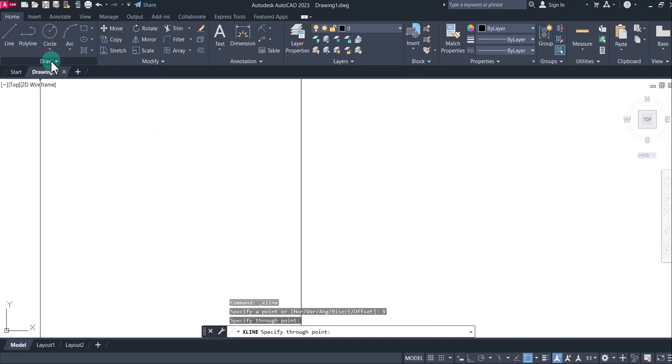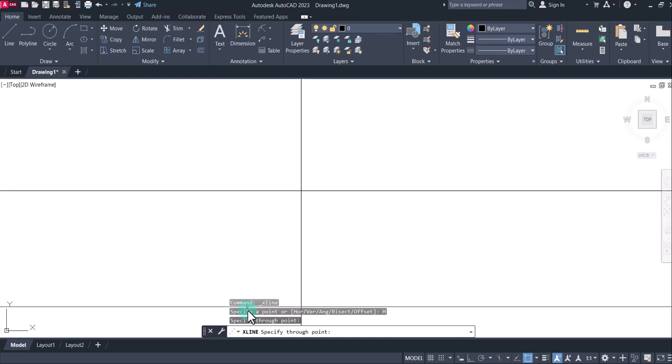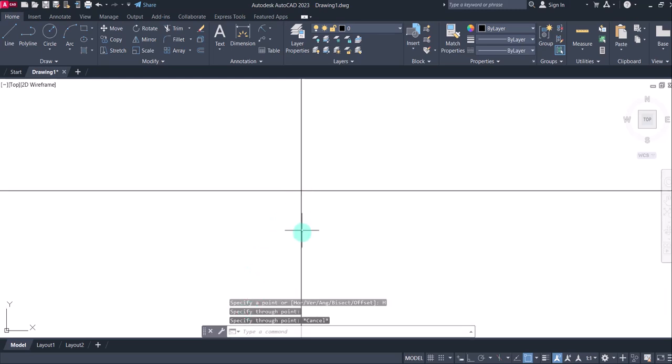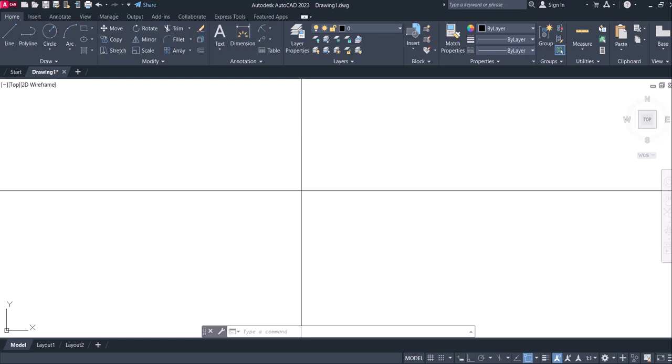Okay, if I go to the arrow on that draw again, I'll pick my construction line again. I'll choose horizontal this time. I'll place my horizontal line at a convenient point. So by placing the vertical and the horizontal lines, I'm able to draw my first center line, using this as a reference. This vertical line and this horizontal line is what I've drawn in my AutoCAD.